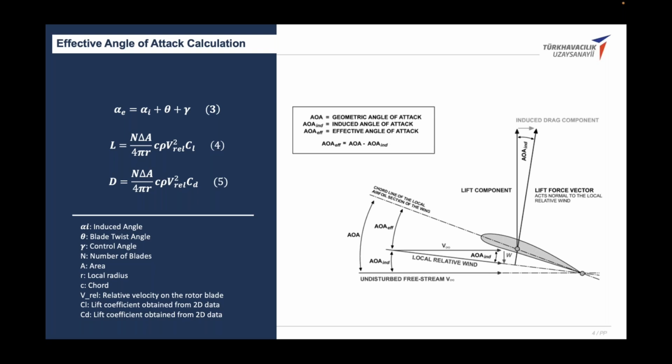we multiply dynamic force with lift coefficient and drag coefficient. In that formula, in the BEM method, we calculate CL and CD, lift coefficient and drag coefficient, from 2D data. And you can see the first term is called solidity. Solidity means blade area over actuator disk area. So you can multiply with solidity, and you get the aerodynamic force in each node.